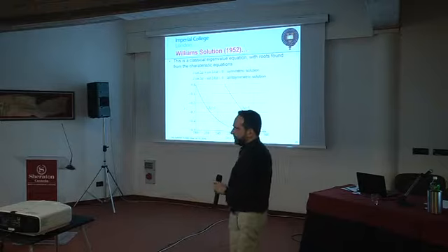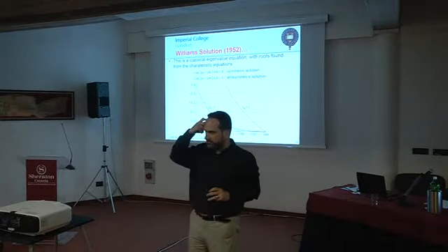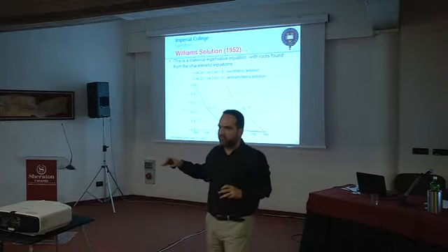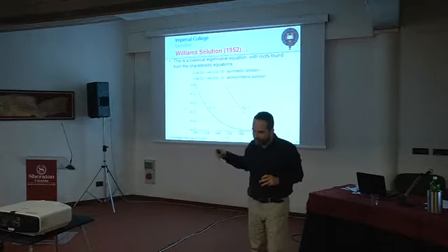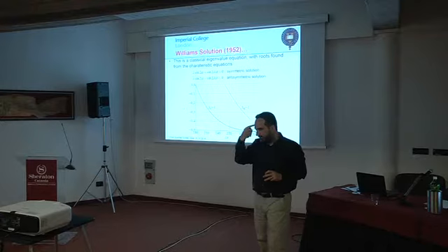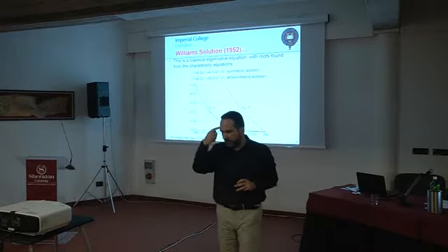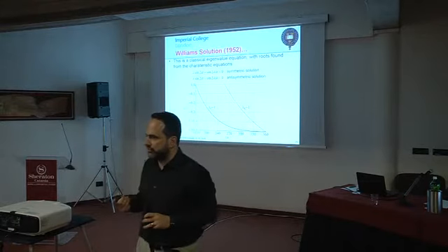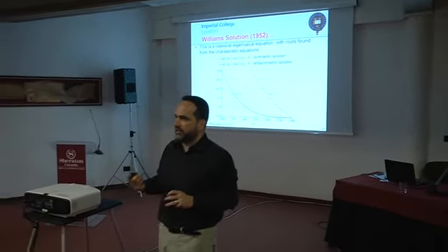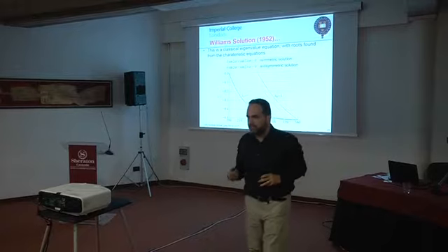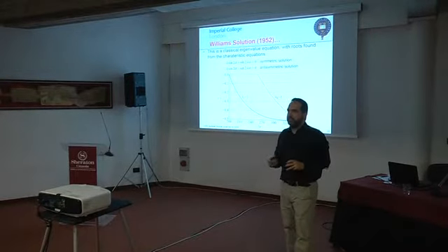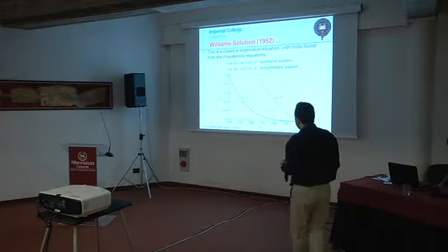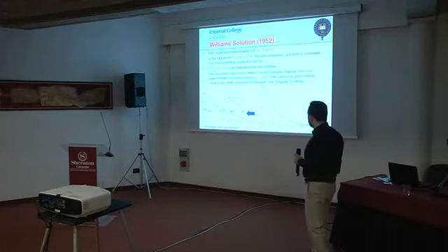And that's important because, as we're going to talk about later, it allows you to understand mode dominance, which mode dominates depending on the load for different notches. So the difference is, for a crack, you always know both mode 1 and mode 2 have the same strength. Now for a notch, that will not be the case. And because that is not the case, the treatment you have of a notch must be different from the treatment you have of a crack. And that's what we're going to do later. So this is really fundamental.